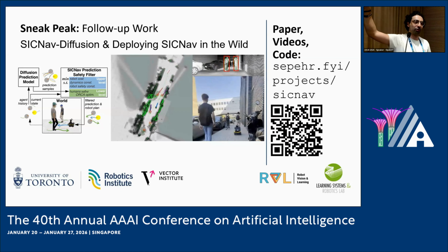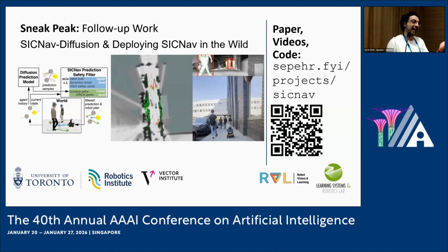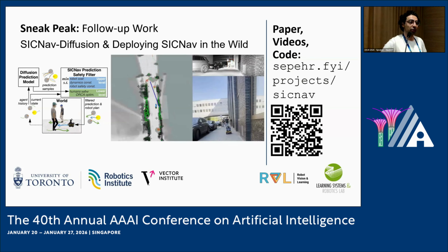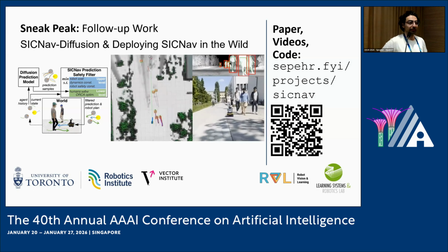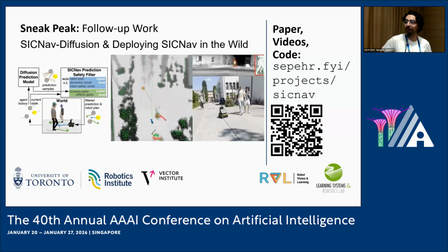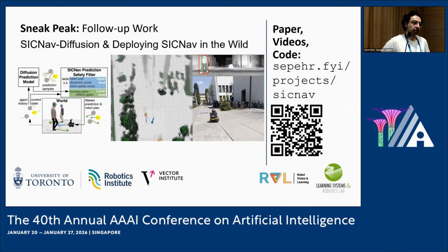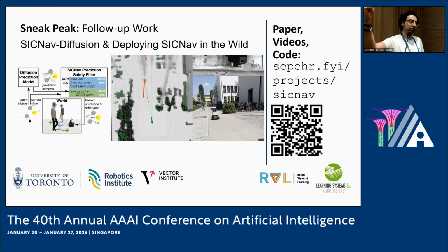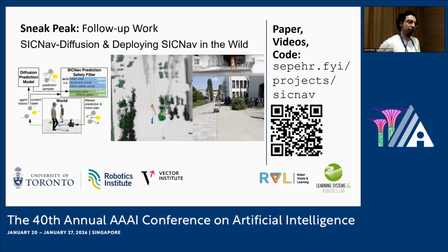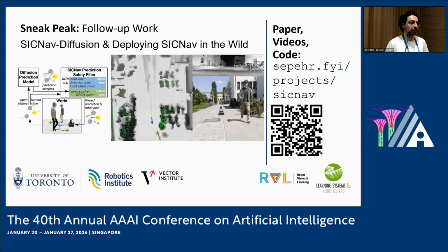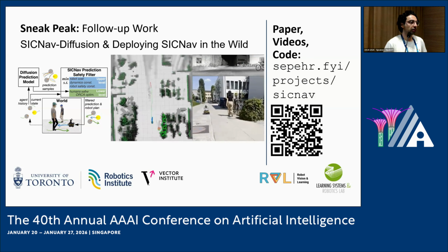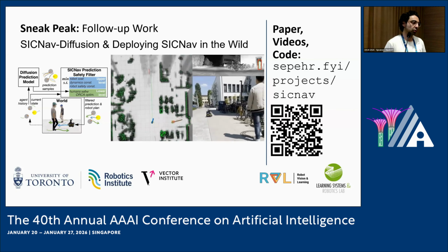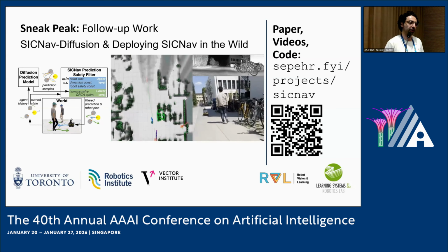These are actually from Ouster LiDARs. They can form this image that's actively collected. We use off-the-shelf YOLO trained on COCO, and it works decently well to detect the humans. Then we get the depth position, the bird's-eye-view 3D position of the humans, very easily that way. But for the real experiments of SICNav, it was just for the TRO paper in 2024, and it was in the motion capture environment.